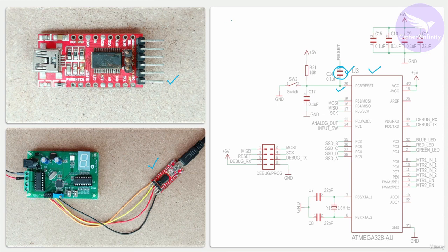We discussed that when you have to program the code in this microcontroller using USB ASP, in that case you have to remove this 0.1 microfarad capacitor and you have to solder a 0 ohm resistor here, or you can short the two pads of the capacitor. So that's basically in case of the USB ASP programmer. But now that Arduino people are actually using a USB to UART converter in order to program the Atmega328 microcontroller, that's the reason we need to connect this 0.1 microfarad capacitor, and one terminal of this 0.1 microfarad capacitor will be connected to the DTR pin.